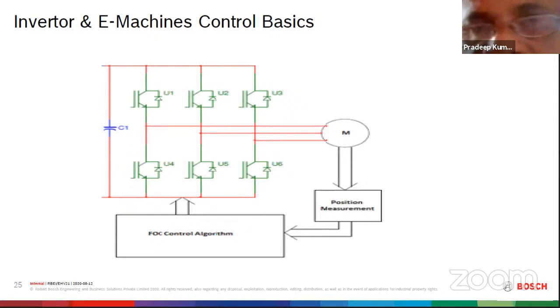The disadvantage of the DC machine is that it has a commutator, and it can have a lot of maintenance problems. It can have some spark during the mechanical commutation. So we wanted to make the AC machine take the best from the DC machine. That means you can separately have field and armature control, but at the same time you don't have the commutation. In the AC machine, you don't have the commutation. So we need a FOC algorithm which makes the AC machine work like a DC machine, so that it is very easy to control.